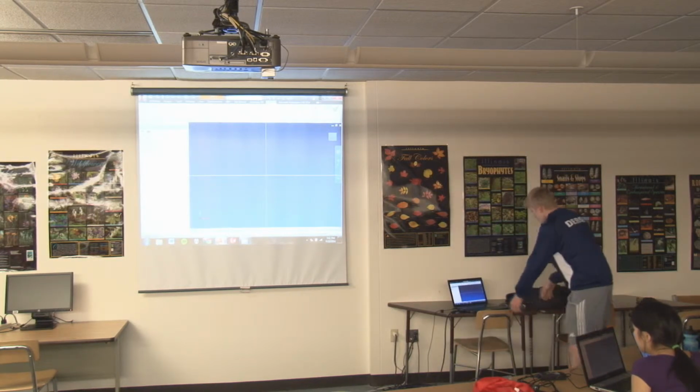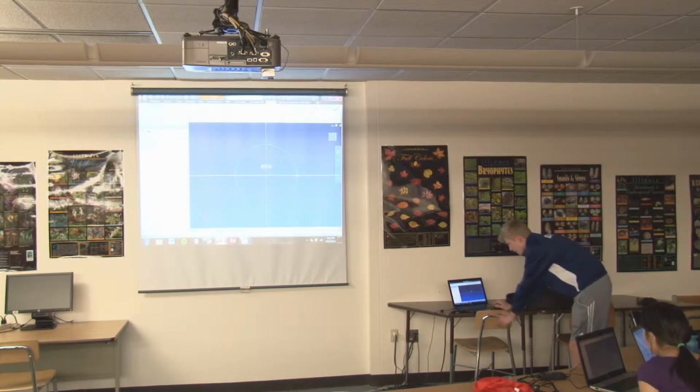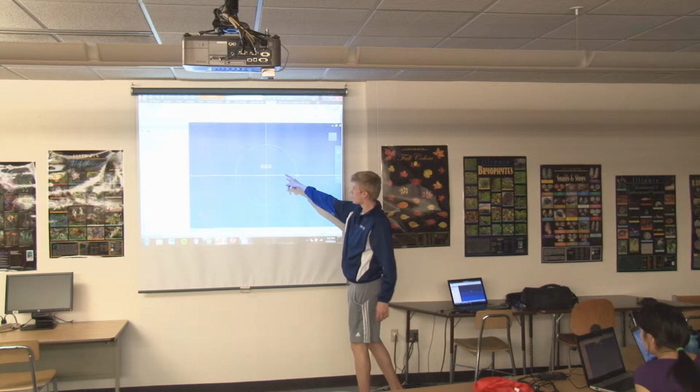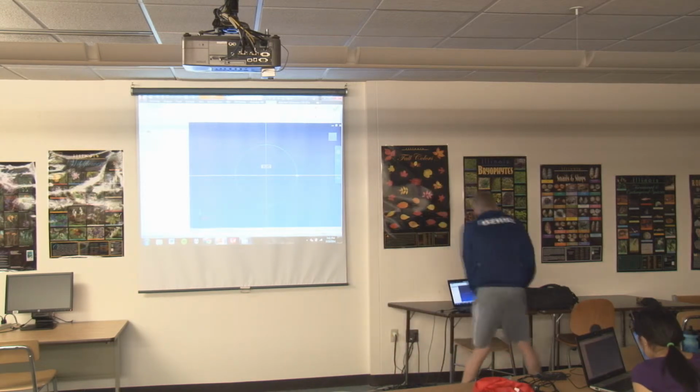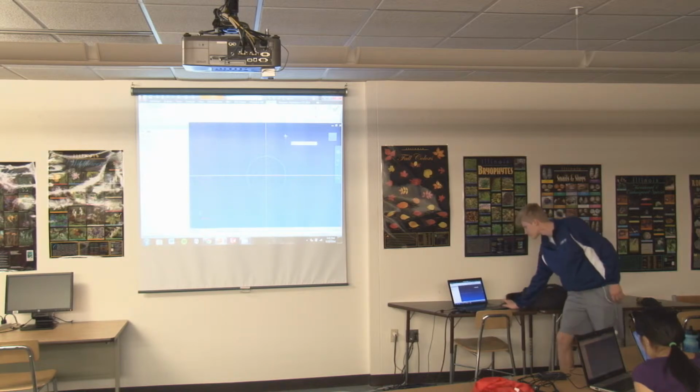So starting with the basic structure, you can click the circle tool, and then when you click on any feature of the CAD, that first click will be the center point of your circle. And then from there, you can drag it out to whatever dimension you want. You can manually enter the dimension right away because you see the number is highlighted there. So let's say that this is 0.5, and it'll create a circle of that dimension.